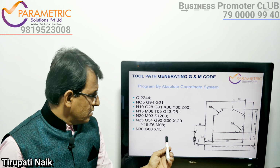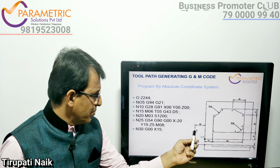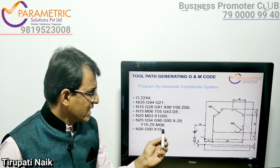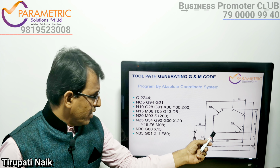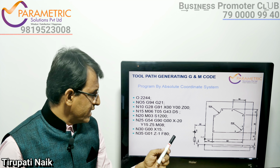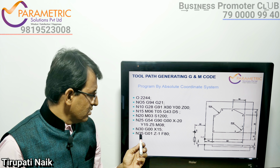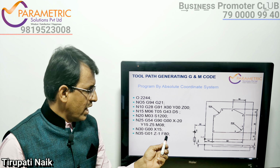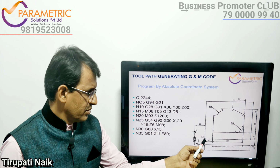After this, block number N30, the rapid traverse tool moves 5 mm above from this position to the first point with G00 X15. Then from 5 mm above, the tool moves inside with a depth of cut of minus 1 mm. So the block number is N35, Z minus 1, and feed is 80 mm per minute.